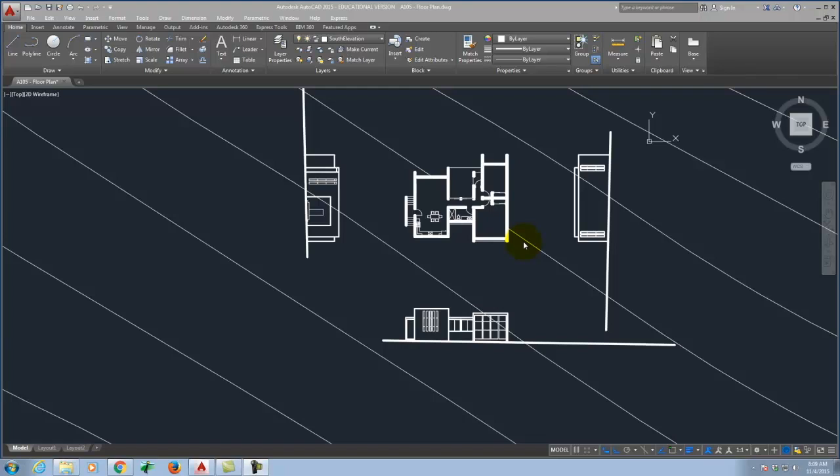And so what we've been modeling in thus far is called Modelspace. And it's full scale, we're just drawing. And it's identified by a tab down here at the bottom of the screen that's called Model. Everybody see this tab in their AutoCAD? If you don't, you might have to turn it on. Sometimes it's disabled by default, and I wasn't sure whether all the computers would have it.